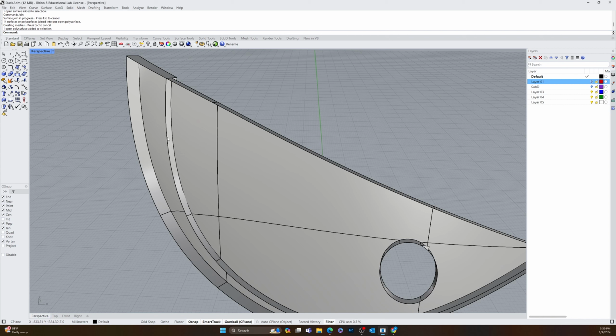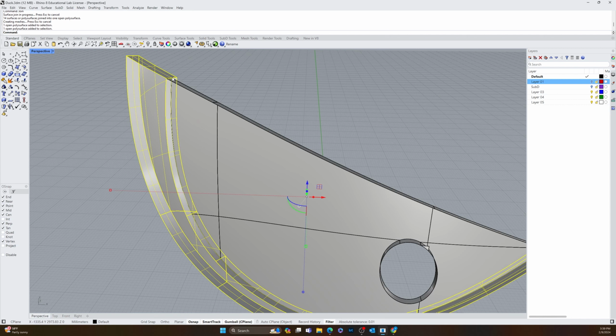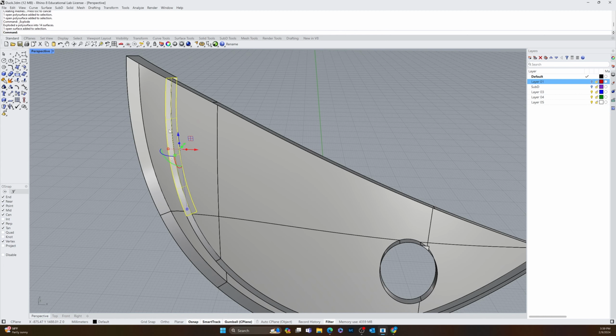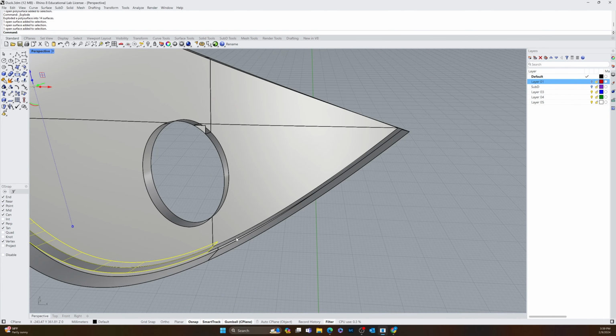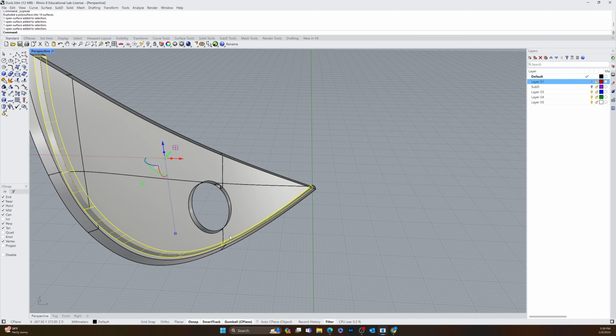So now, because this is all one piece, there's this weirdness where these two corners go edge to edge right here, and sometimes CAD programs have a problem with that. That's why we need to explode this, so it breaks it all into little pieces, and then we join just the section together that we're going to cut out. Join that together. So we have a simple cutting edge that lines right up with our other object.